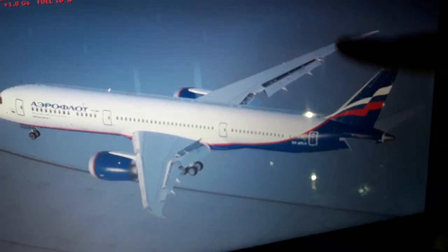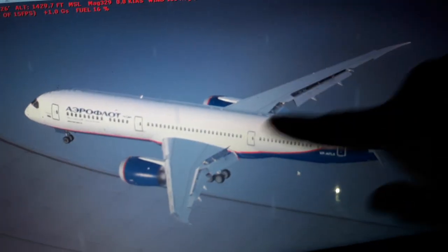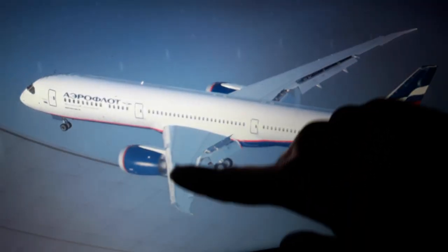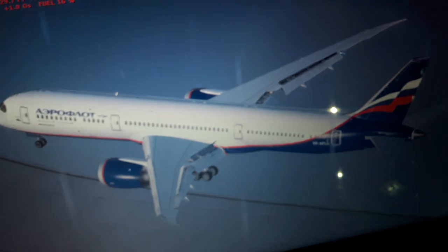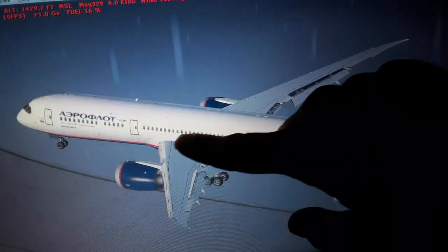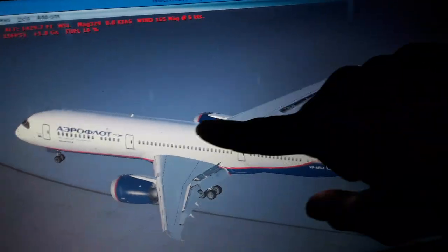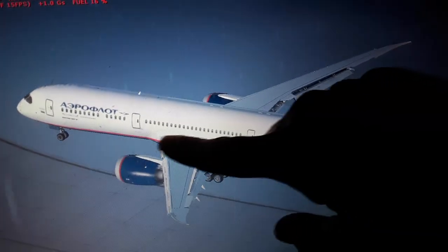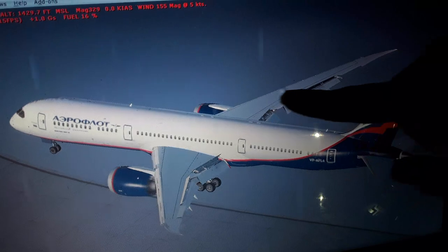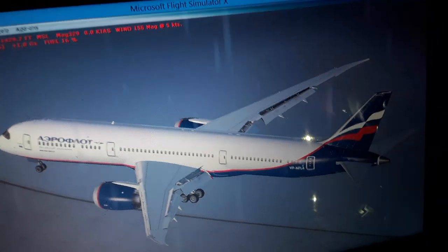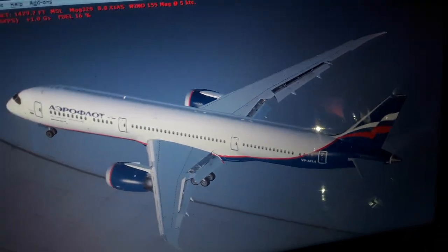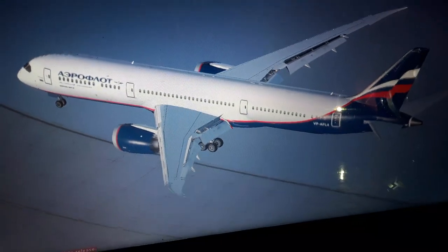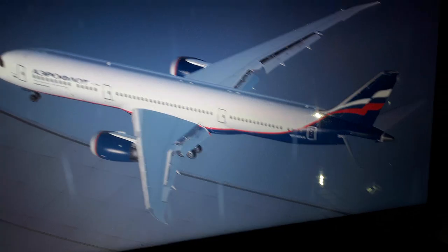You can see the surface area of the wings holds the aircraft weight when we fly. We have the mean aerodynamic chord position, about here is the maximum aerodynamic lift position. It is the position where we calculate the center of gravity. Also the stall will begin here. The airflow from the top surface will become detached for a given angle of attack of the aircraft, airspeed, altitude, and flap setting. We're gonna have to avoid the stall speed all the time.